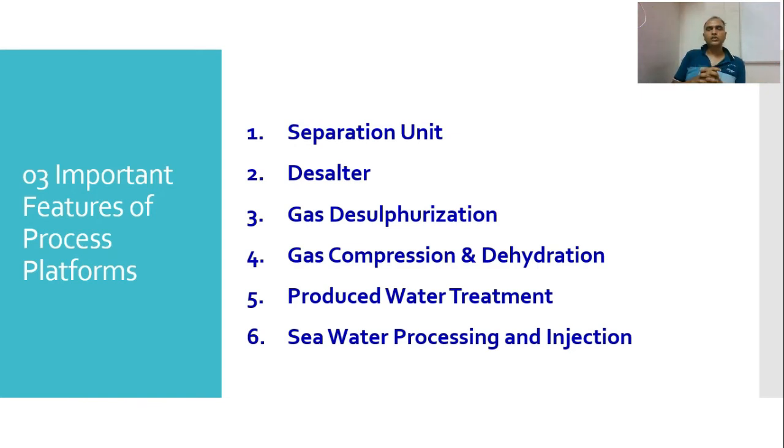Okay. So in the same way, the well fluid is a mixture of sand, water, crude oil and dissolved gas. When it comes out and is sent to some tank, it also creates that same soda effect. So first and foremost important part is the separation of crude oil from gas, produced water, which is the sea water coming with it, and sand.